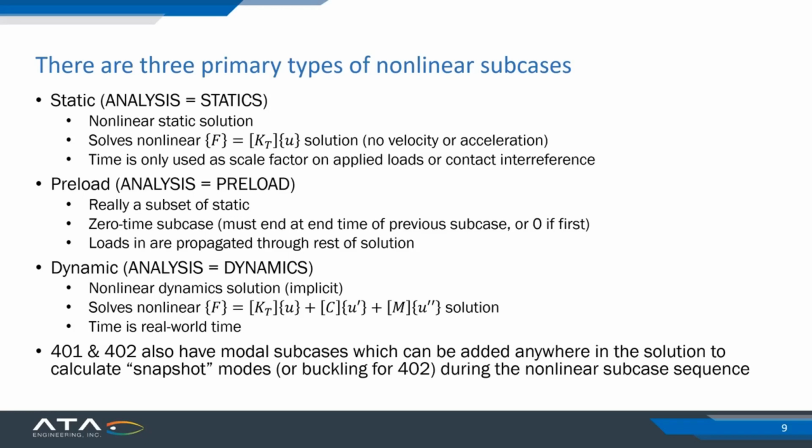So it's literally preloading the structure, so there's no reason you would want those loads to go away. That's the intent of that subcase. But it does occur over 0 time. It still will scale the loads. There's a load factor that it does, and it will ramp loads throughout that preload type subcase. But it's just considered a 0 time subcase because it's not intended to be any part of your nominal load sequence if you're doing one of those.